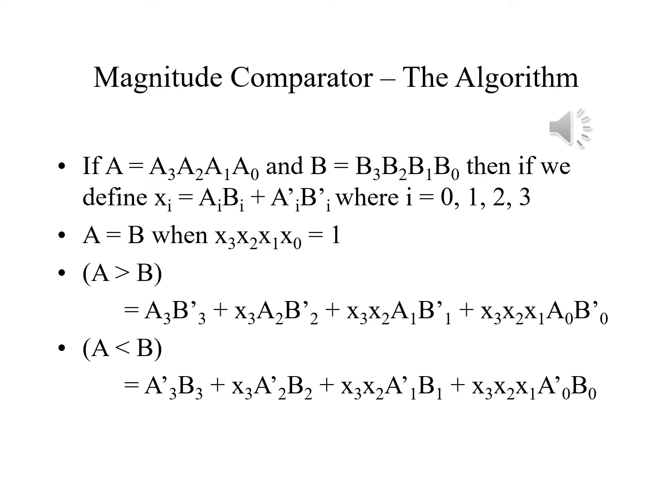If those 3 ANDed together give me 1, then again I have that. If the top 2 pairs of bits are equal, then I'll take a look at bit 1 in both numbers. If all 3, then I'll look at A0 and B0 prime.